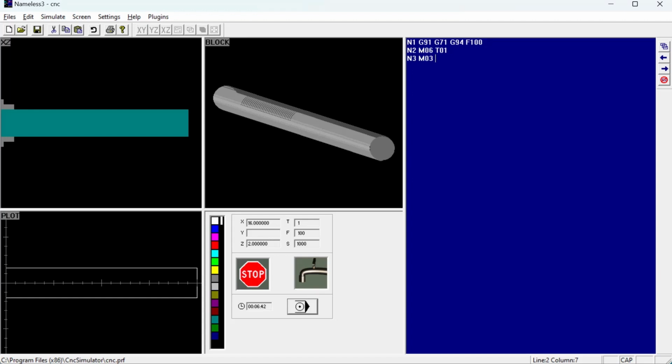And then we need to specify the speed of the rotation in RPM, which is done by using S. And we need a speed of 1000 RPM. So we'll type in 1000 RPM. Then we need to mention the coolant type. So there are two types. One is mist coolant and the other one is flood coolant. We are going with flood coolant, which has a better cooling action.